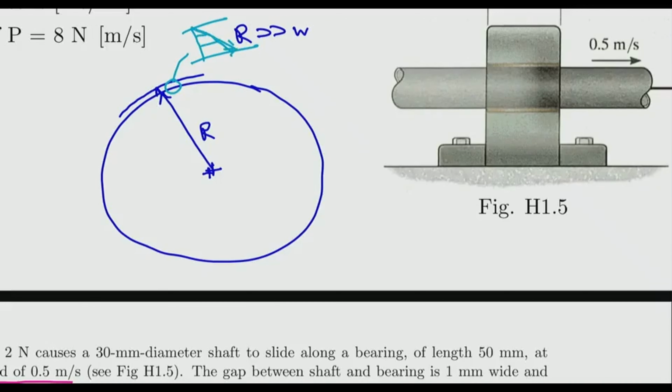So it's a very thin gap and a very large cylindrical surface, so that the fluid essentially sees something that's sort of flat. That's why it's simplified like that. If it wasn't, and we can consider a flow like this in Chapter 6, you have flow through an annulus, and that's a whole different thing that has to consider the curvature of the problem.